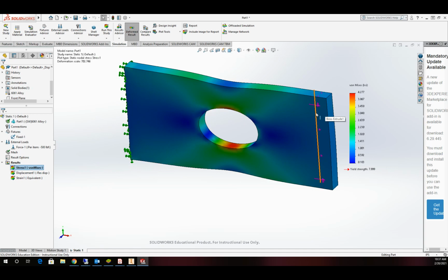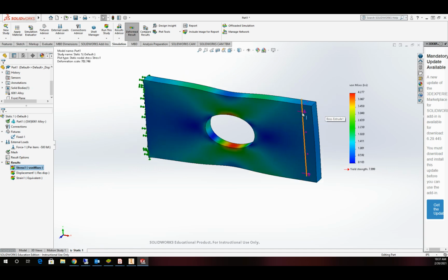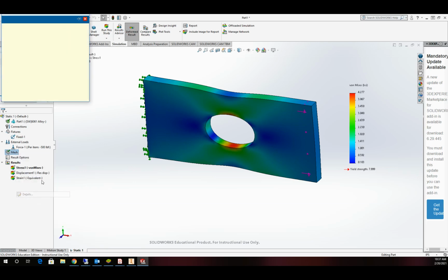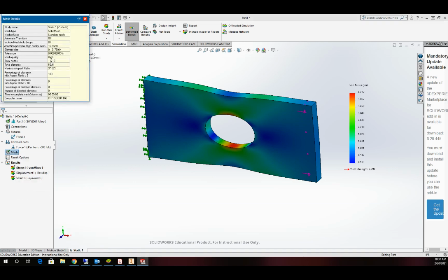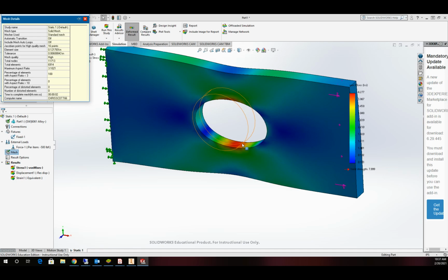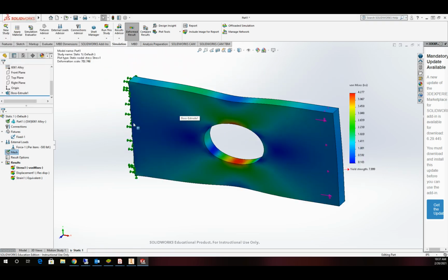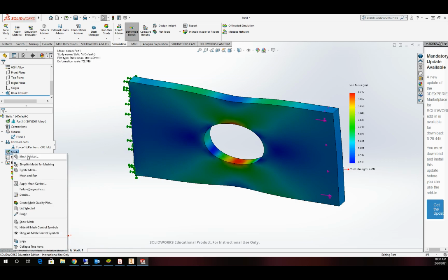4,277. At this point, if I'm going to use the global strategy, I would just record my values for my mesh, which we saw back on that detail sheet at about 11,000 and 7,000. And then I would record my value here and indicate kind of where it was at. With this approach, my next step then would be to edit the mesh.